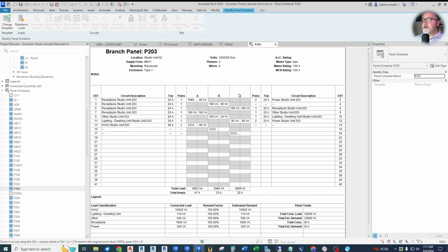So this panel schedule was created with a panel schedule template. And as you saw, it used the default template. So now let's get into how do we actually edit these templates to make this look different. Perhaps your company standard applies some different columns, or you have things arranged differently, you numbered differently even. You have different things in the header. So we can change all of that.